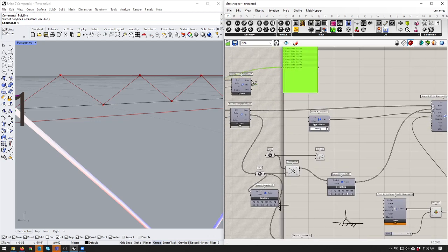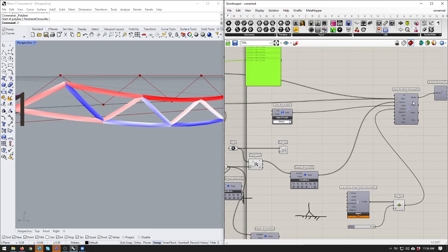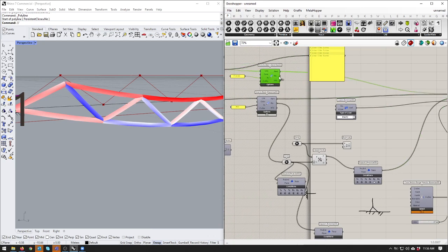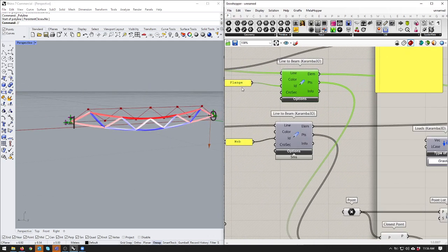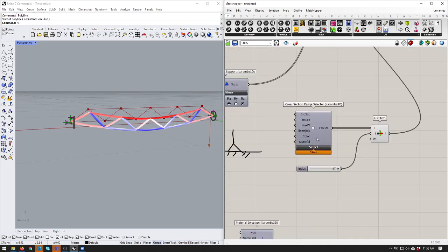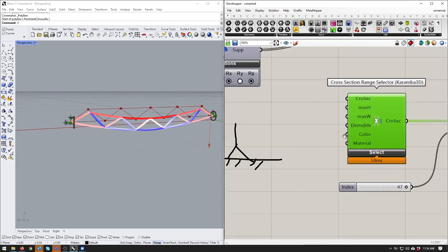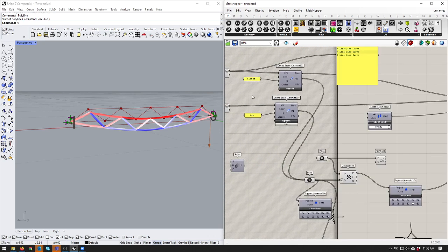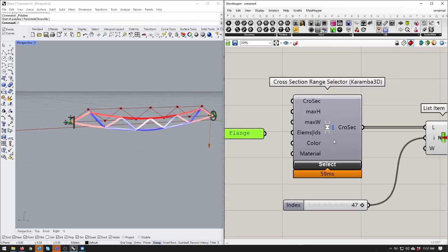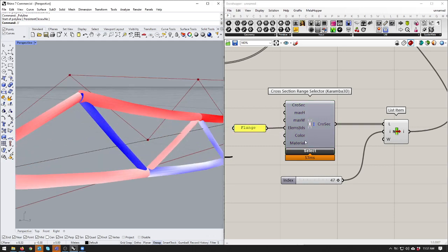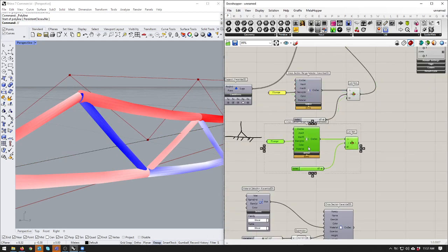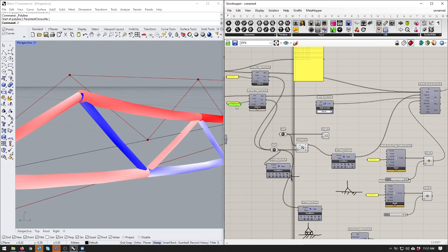And these elements now need to plug in and merge as they go into the assemble model. And as well, we'll probably also need to do that with the points for the supports and so forth. In doing so, we've assigned some IDs so that when we are running these cross sections, we can assign these same names to the cross section. So we can say this particular cross section here is going to be flanges, and this cross section is going to be the webs.